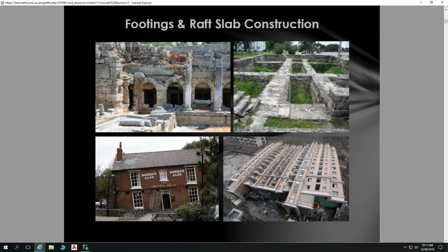that diminishes the extent to which that steel will stretch before it holds. Because if we get some steel, we can stretch it a little bit and then it becomes harder and harder to stretch. So if we stretch it a little bit already and keep it slightly stretched, it's going to take those tensile forces a lot more straight away. And then if we provide some compression to the concrete already, then we're not going to have to deal with any compression of that concrete when it's under load.